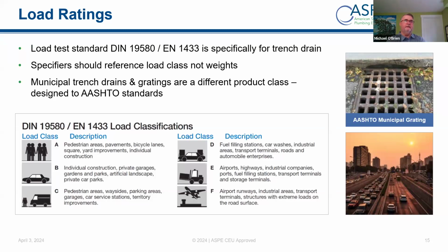They would typically fall in that same A, B, C, D for extra heavy duty, and E for special duty. That is a standard that you would typically see on drains designed for, say, food and beverage facilities, where the type of traffic they're going to see is forklift and that type of thing. Something to keep in mind.